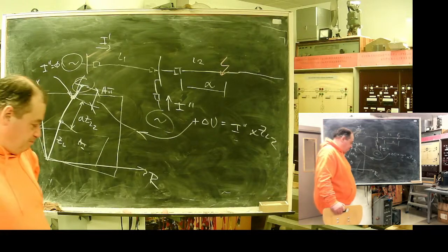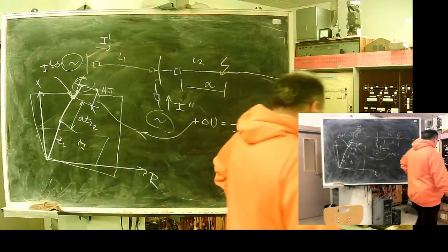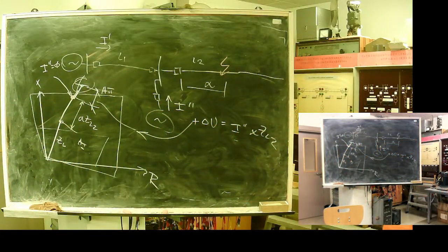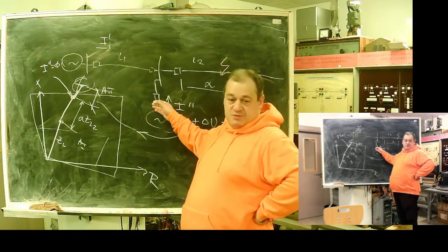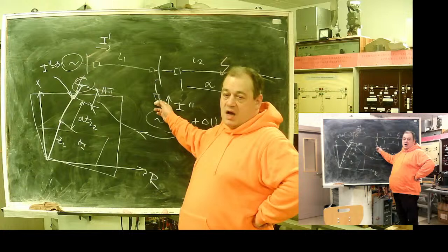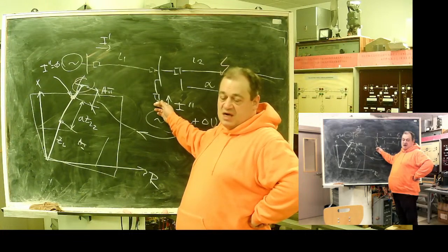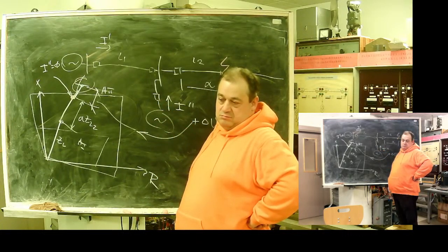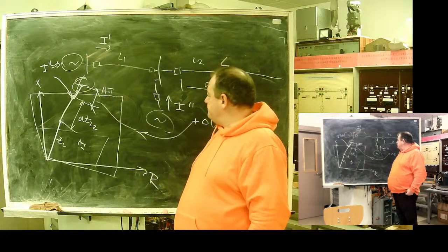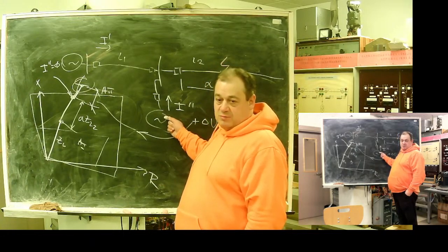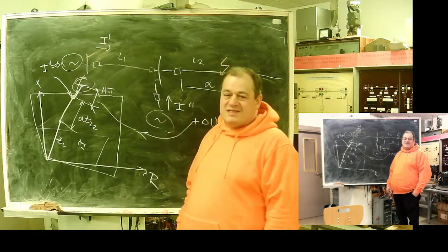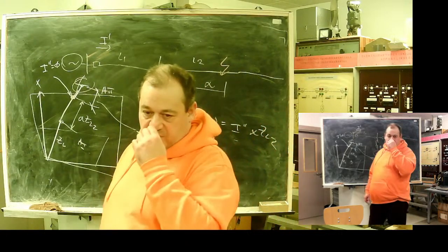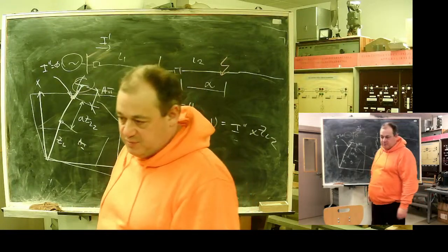Where is it dangerous? In case this source trips first, the current distribution factor immediately rises to 1, and if we calculated our settings assuming this source is operational, or it may be unavailable or something like this, we will see instant elongation of our zone and possible non-selective trip.